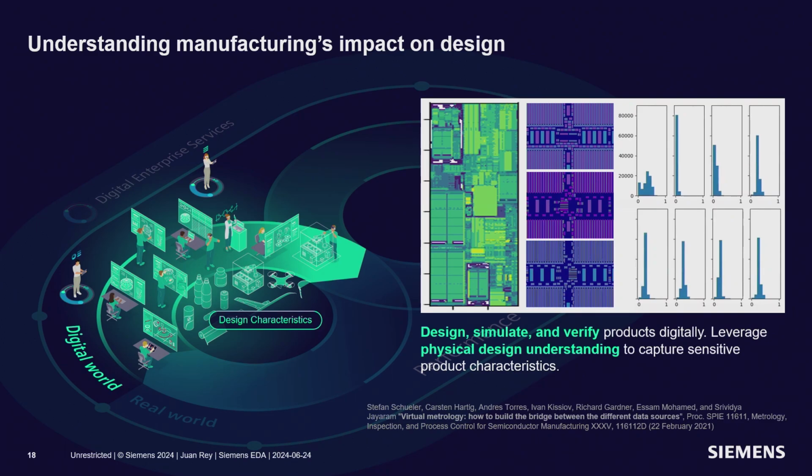What we have here in the inset to the right, on the left side of the inset, is essentially an image of the whole chip, of the whole design, where the different colors show density of polygons. So when you see the more solid colors, in particular in green, a larger density; the colors in blue, a lower density. The second part, at the center of the slide, is essentially some of the data processing that the design is going to go through. What you see there at the center are the processes that are done when you need to do double patterning, which is essential for pretty much any advanced CMOS technology today.